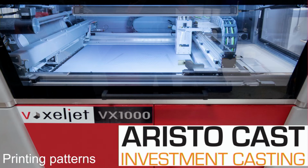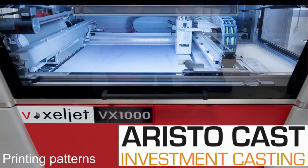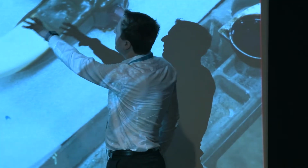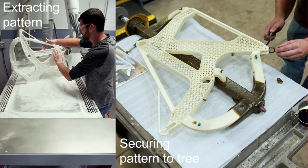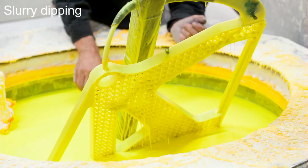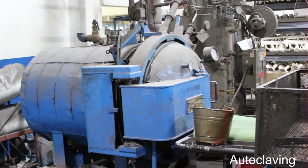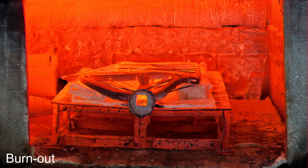So this is the VoxelJet printer. You can just see a slight outline of the seat frame there. We tend to print all the channels in there as well to help the material flow. So you can see that here. So we've got that pattern which has come out of the machine here on the left, and it's got all those channels printed in there, and it's all ready to go. So the next step is actually to dip this in a slurry. So it's a ceramic coating applying to it. And then we do a quick sand coat on that. We autoclave the component. And then we burn it out.